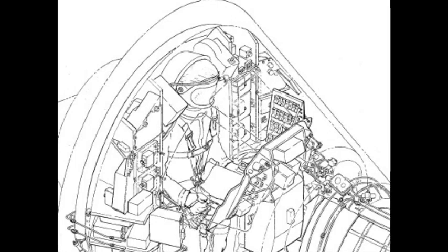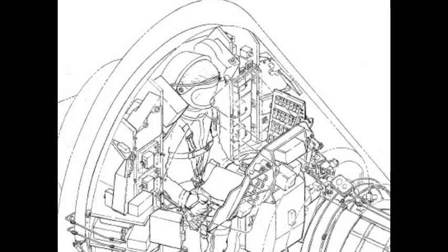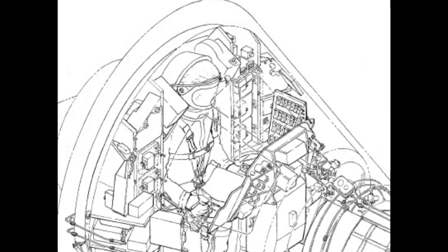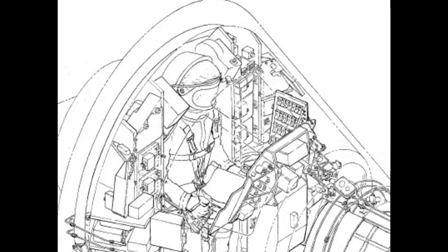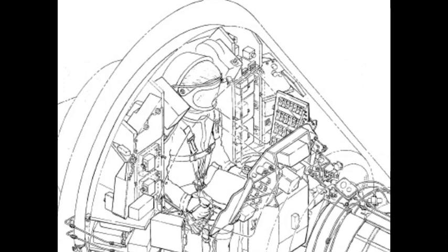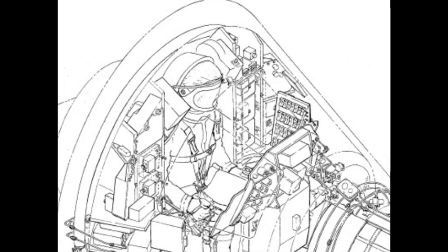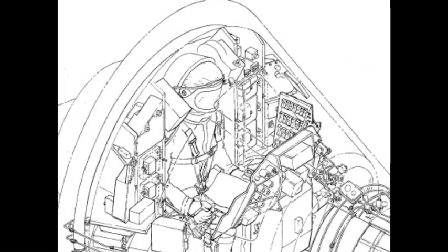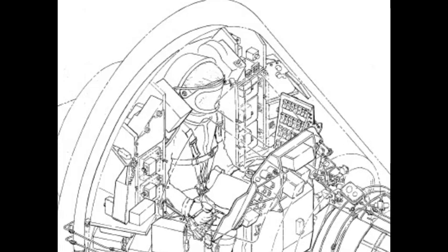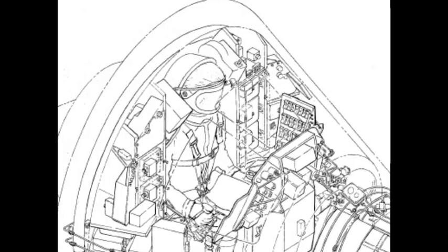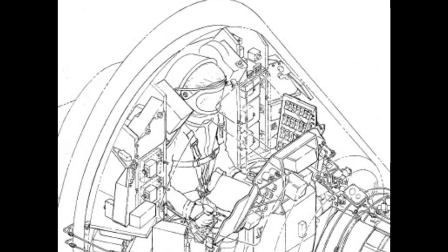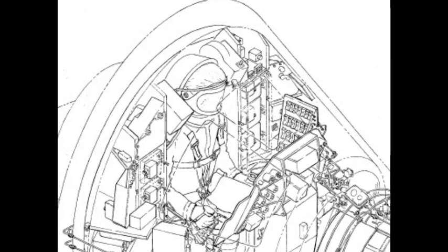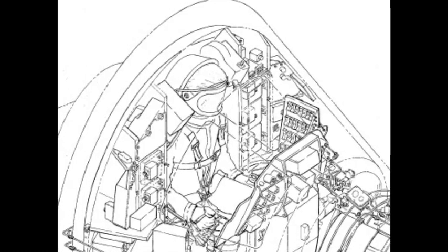The main cabin window consists of 4 glass panes sealed in a titanium frame attached to the cabin wall. The glass panes are spaced and independently sealed to provide a pressure seal between the panes. The outer cabin window consists of a glass pane sealed in a titanium frame that is attached to the capsule outer skin. The outer pane conforms to the curvature of a capsule conical section.